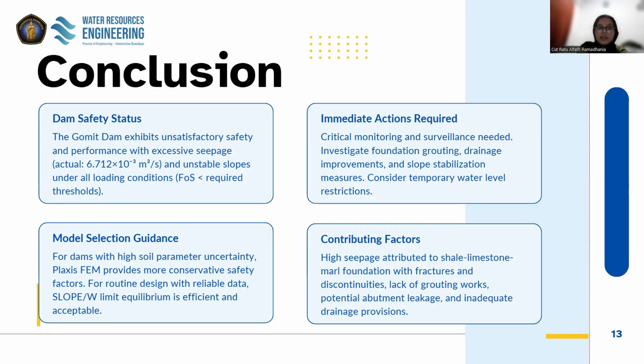And for the model selection guidance for dams with high soil parameter uncertainty, Plaxis finite element method provides more conservative safety factors. For routine design with reliable data, GeoStudio limit equilibrium is more efficient and acceptable. And for the contributing factors, high seepage attributed to shale limestone foundation with fractures and discontinuities. So there is a lack of grouting works, potential abandonment leakage and inadequate drainage provisions.